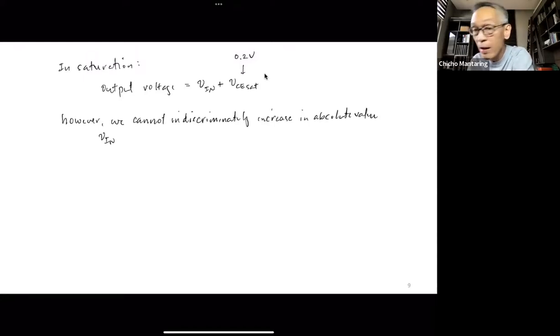Because if you increase V in to way beyond the conducting voltage, you're going to be overdriving your base emitter, no? Think of it as a diode. This is your base to emitter. So your diode characteristics look like this, where if this is silicon, this is about 0.7.